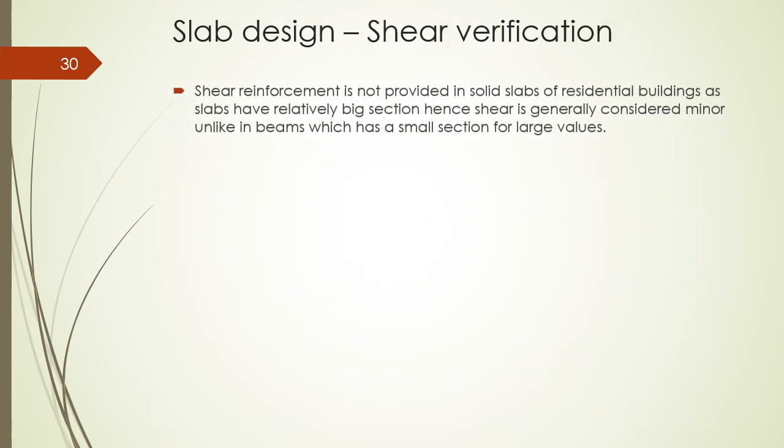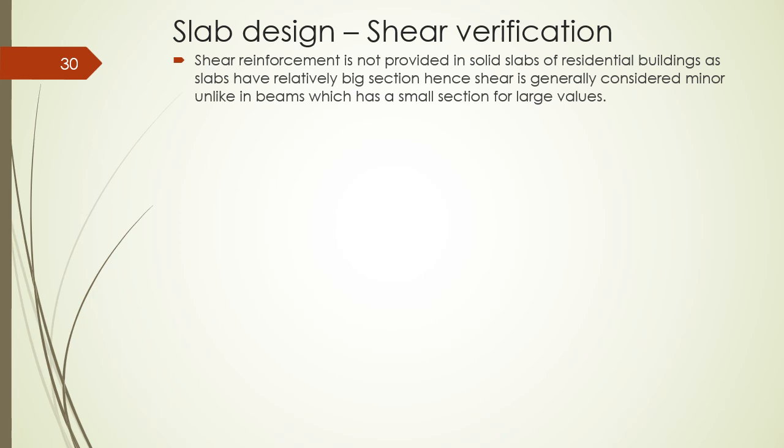After that, ideally we should do some shear verification. However, shear reinforcement is not provided in solid slabs of residential buildings. Since slabs have relatively big sections, shear is generally considered minor, unlike in beams, which have a small section for large values of loads.